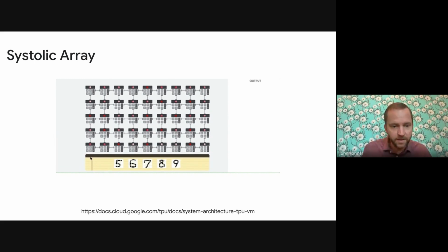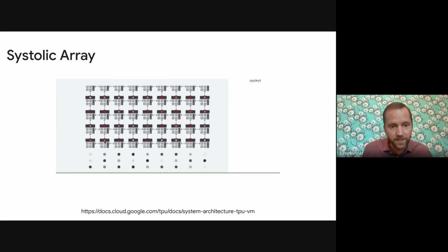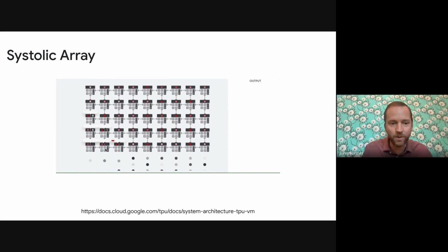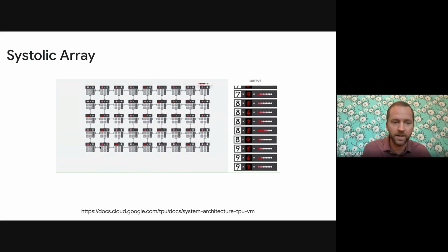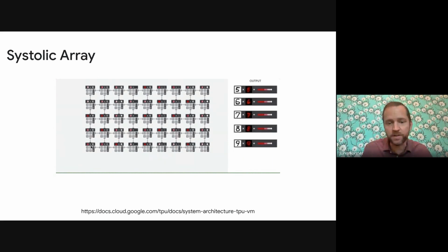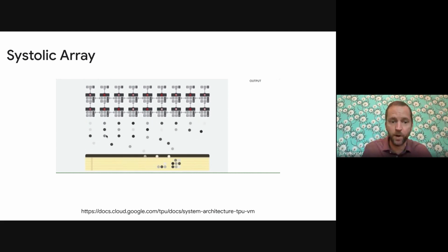This means that data arrives on the first one, it does its computation, and the next 2 elements are fed at exactly the right time with just the data they need in that clock cycle to be able to do their part of the computation. This means that intermediate results are never sent to memory or never stored in some temporary register. They're sent directly to the neighboring component.